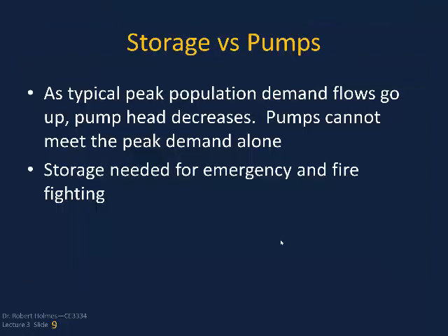So thinking about pumps in the system versus storage, the reason we have storage is that it'd be cost prohibitive to design and put in a number of pumps that would meet your peak flows and everything that we put at you, including fire flow. In addition, the pumps are also dependent upon electrical power. So be it a backup system with generators or the main electrical grid, you can have problems with things going down, the pumps failing or whatever.